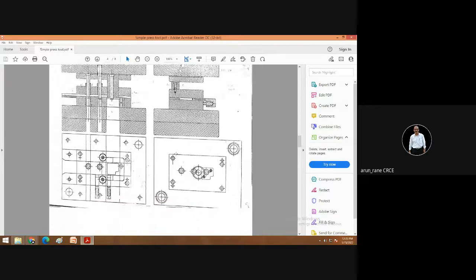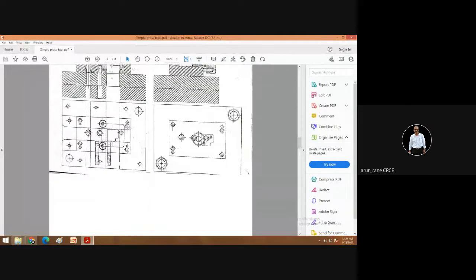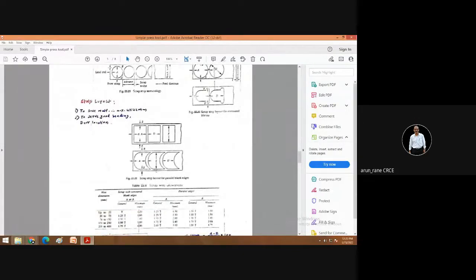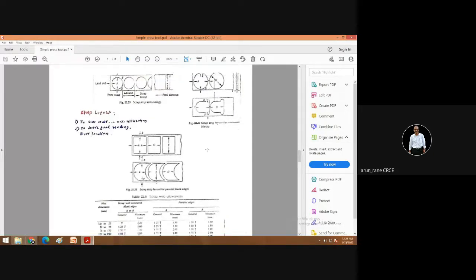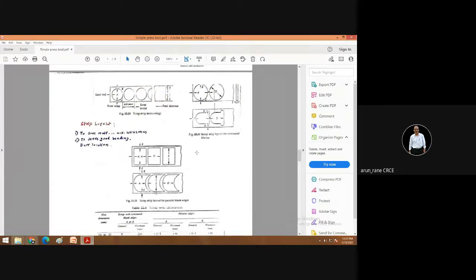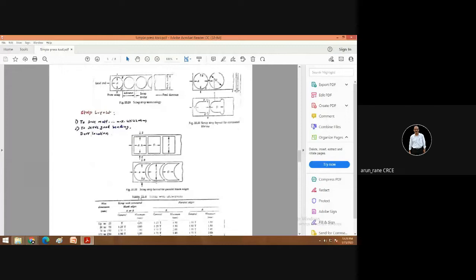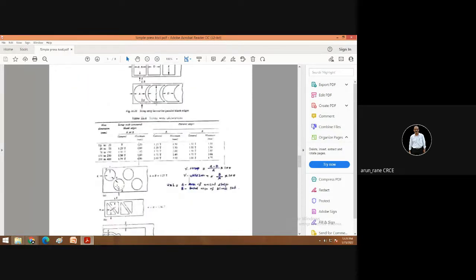In order to have better clarity, it is advisable that you draw four views. And I told you what the four views are. These are the different strip layouts. Suppose your component is round, or rectangle, or of this shape. Look at this shape, so you have to suggest a different layout. Now, an alternative arrangement for a circle: if I want to improve the percentage utilization of the strip, then I can go for this design.